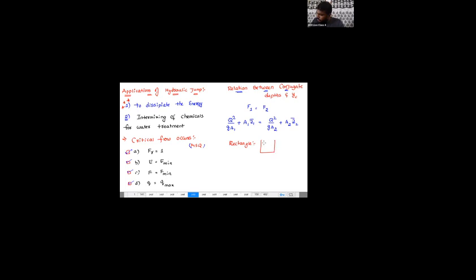This is channel flow, and in the case of a rectangle, the Z bar is simply y by 2, and if it is a triangle, the center of the triangle from the free water surface, the Z bar is equal to y by 3.